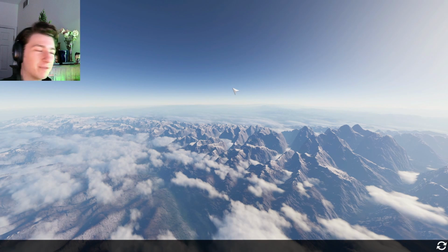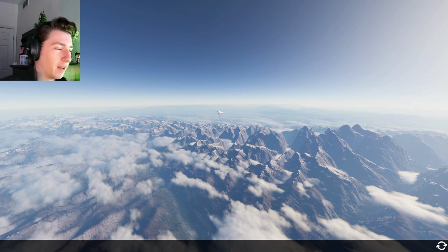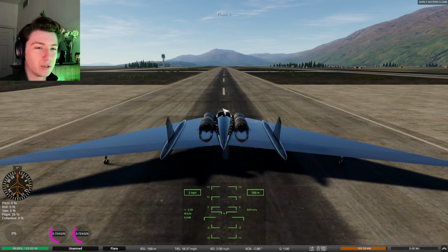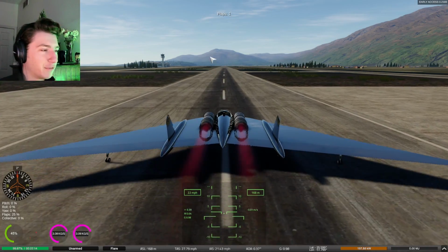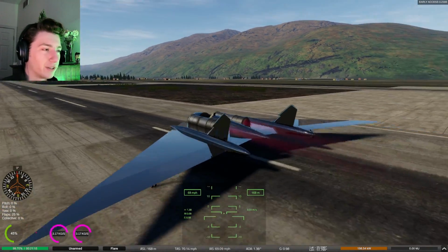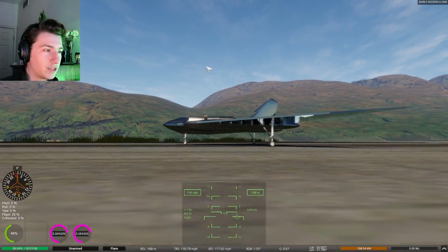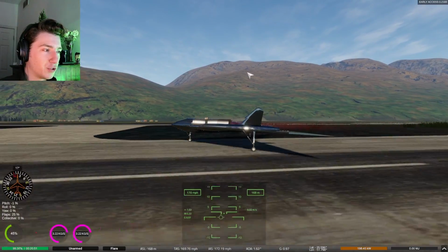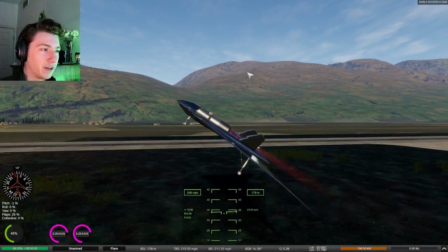Let's try that again. Basically what happens, and there's some science behind this that I won't bother explaining because I don't think you guys will watch it, but basically the control input, you create a positive feedback loop and everything goes wrong very quickly. So let's just, rather than go crazy, let's just trim the pitch upward. There we go.